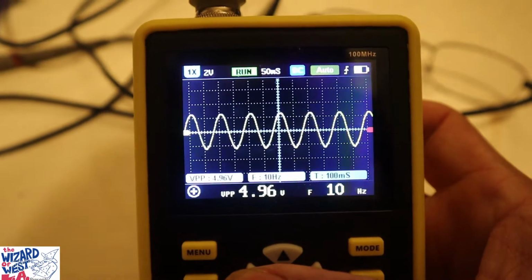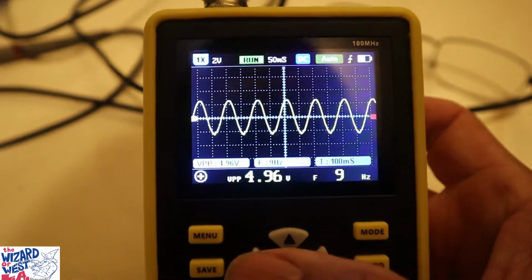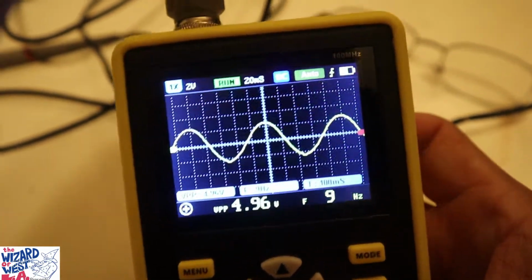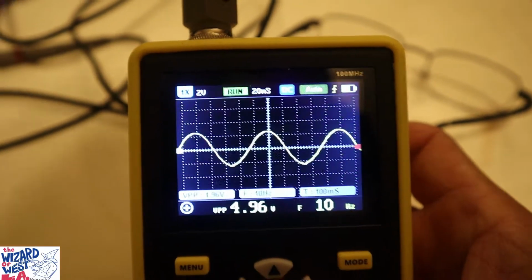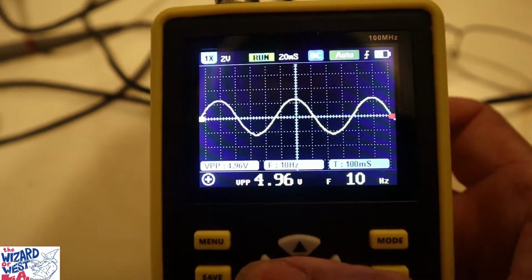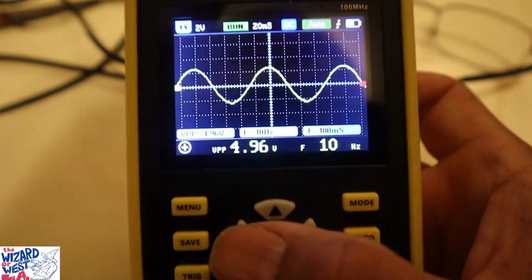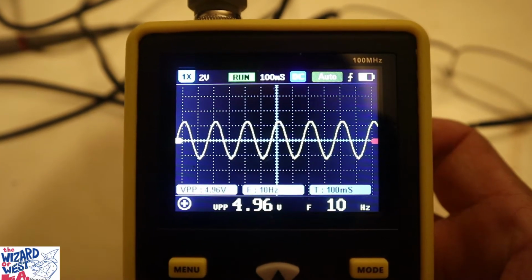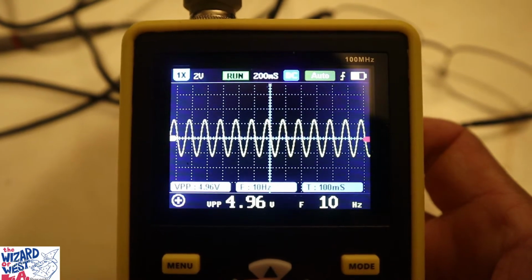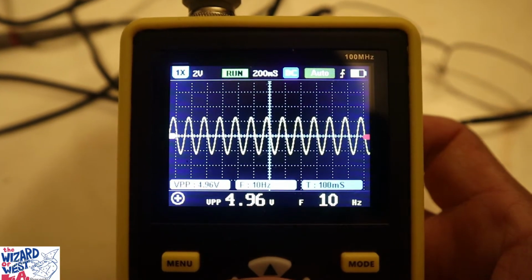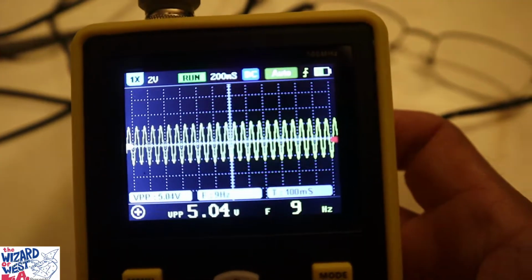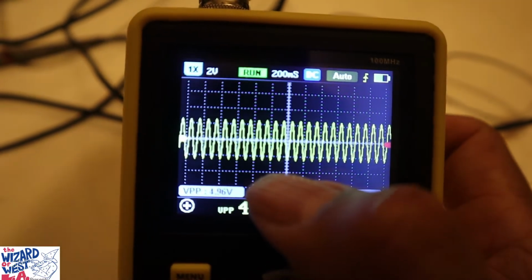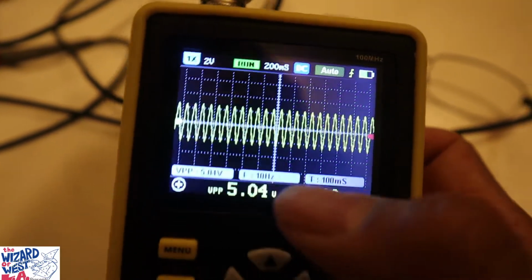Here's the interesting thing you can do with this real quickly: you can adjust the horizontal, which changes the time. If I change the time, we're at 20 milliseconds. I can raise it up. I'm going to push the left arrow, and now I'm at 50. And this is by time. 100, and I can keep going. And 200. And then after a while, you're going to look at too many waves per millisecond. That is measuring each part, each square horizontally is 200 milliseconds.